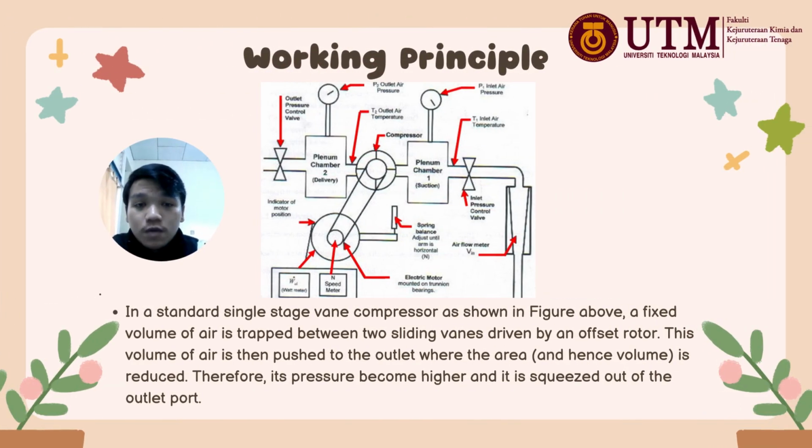Now we move on to the working principle. In a standard single-stage vane compressor, as shown in the figure above, a fixed volume of air is trapped between two sliding vanes driven by an offset rotor. This volume of air is then pushed to the outlet where the area, and hence the volume, is reduced. Therefore, its pressure becomes higher and it is squeezed out of the outlet port.